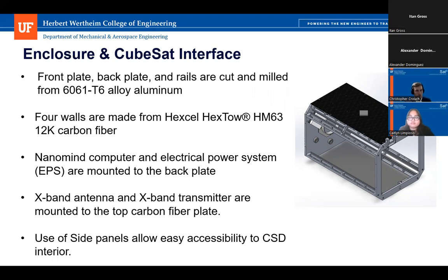And to improve upon many of the existing designs, our CSD enclosure features firm foam rails designed to attenuate vibrations imparted onto the CubeSat by the rocket during launch. Out of existing CSD designs listed in the CubeSat design specs, only 2 out of the 15 include a design choice that directly addresses vibrational attenuation. The foam we selected is a fluoroelastomer foam, which meets both the minimum and maximum temperatures expected during launch, and it meets NASA's requirements for outgassing. One major concern we had was ensuring the friction added by this foam would not negatively impact the launch system, and by specing a firm foam with an ultra smooth texture and a lubricant to match, this challenge was overcome. Next slide, please.